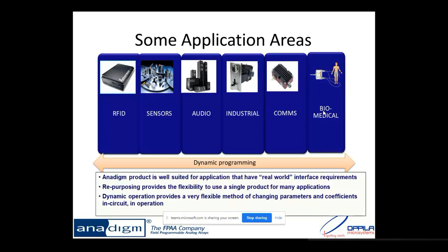We can amplify the signal first, because those are very low voltage signals. We can amplify it, process it further, and get the output. So the most important applications are sensor signal processing, audio signal processing and biomedical signal processing, because it can accept them. Personally, I have fed 200 microvolt signals as an input to this FPAA and amplified and processed them. I have done some simple processing of biomedical signals.